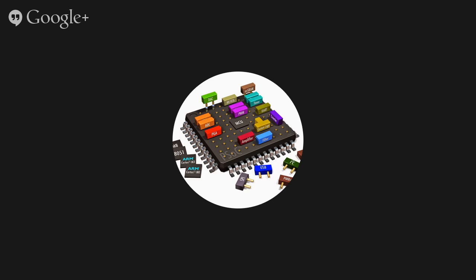And you can see down here that it's put it on P00 in this diagram. One of the cool things is it's actually interactive, so I can drag and drop this to P07 over here if I wanted to. And you can do that with any pin on here. The blue text is the fixed function, so there are certain blocks that work better on certain pins, and this blue text describes what that is. But any generic interface, such as just a pin for driving an LED, can be thrown anywhere on this design.